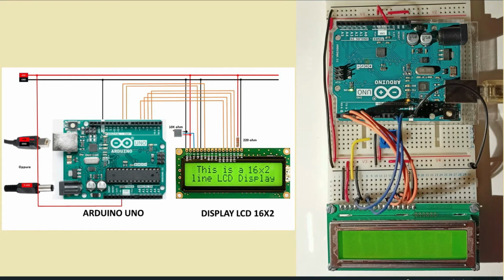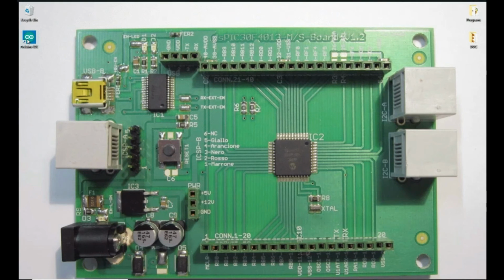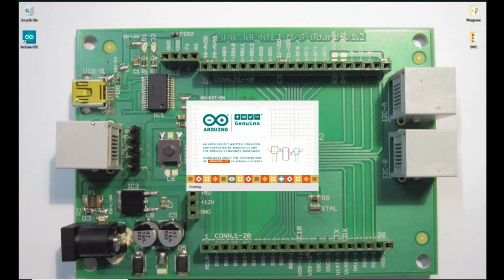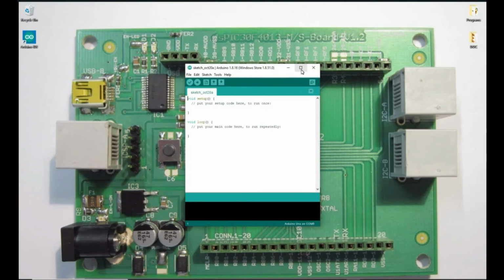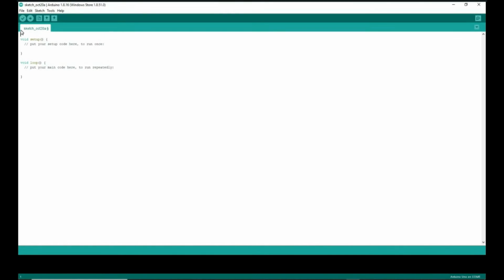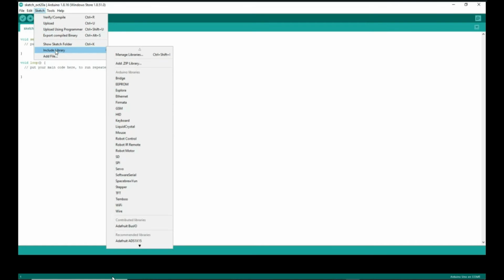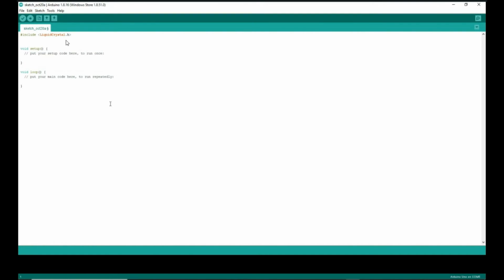to test its operation. We then open the Arduino software. I have the most recent version that was in the distribution, the 1st of August 16. So, let's start right away with importing the library. Go under Sketch, include Library and import Liquid Crystal, liquidcrystal.h. Then let's insert the comment with the description of the parameters of the initialization function.